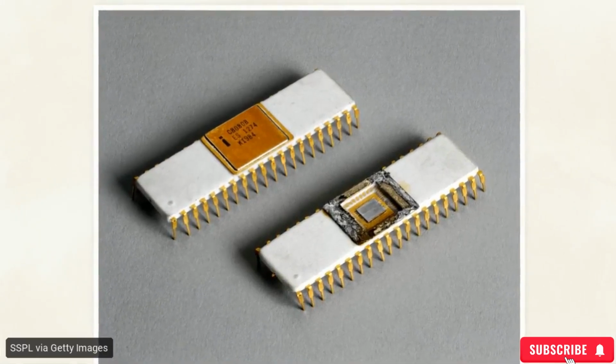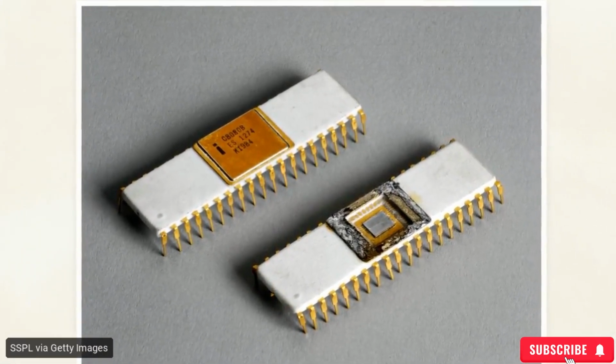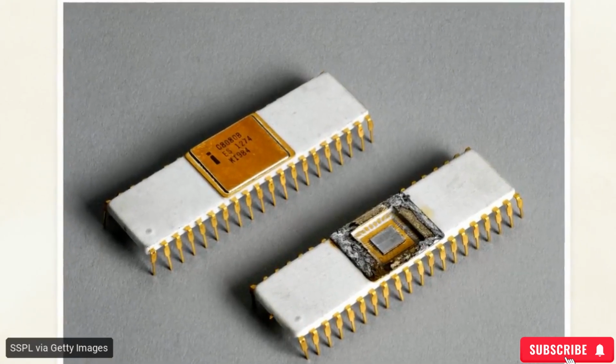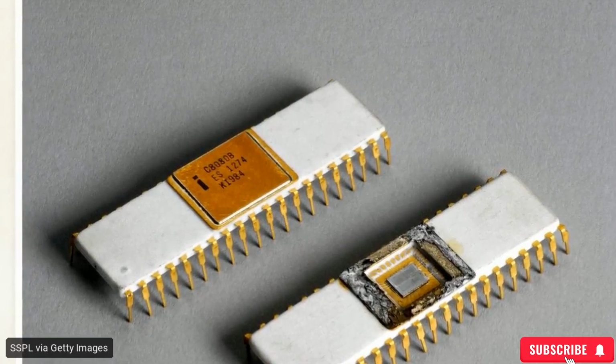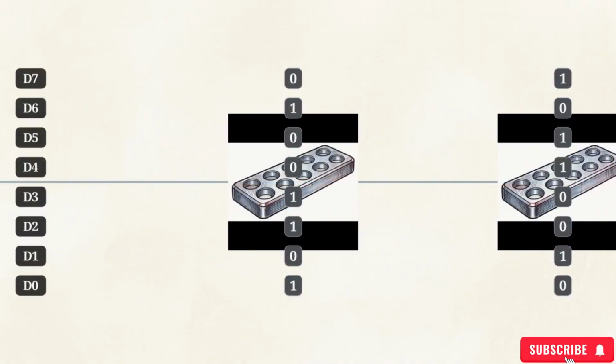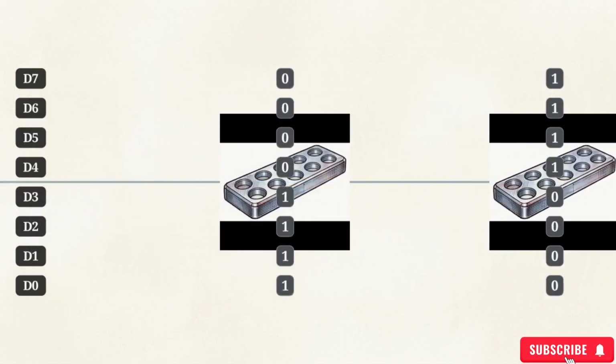A processor like this Intel 8085 is a physical device. It responds exclusively to two electrical states, a high voltage or a low voltage. To process information, the 8085 relies on an 8-bit data bus. Data flows through 8 physical pins, moving as continuous pulses of ones and zeros.